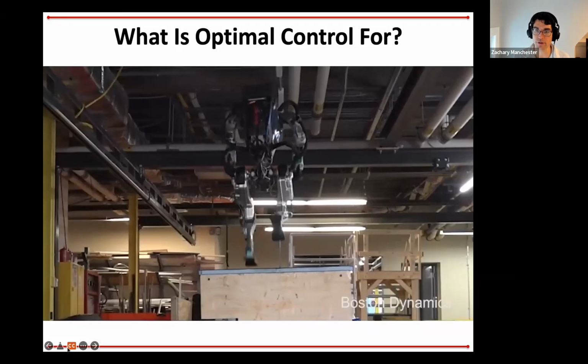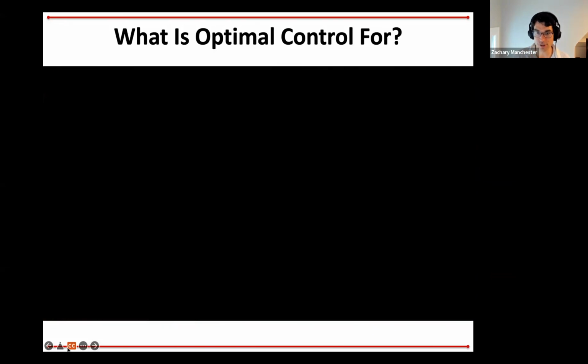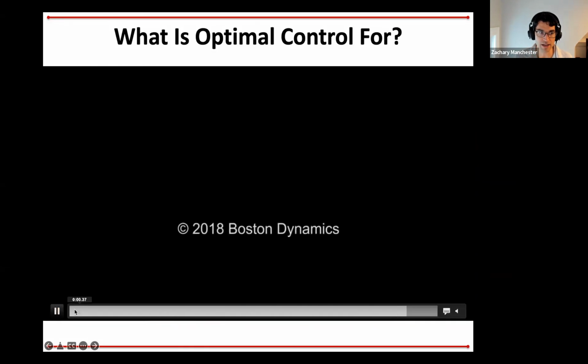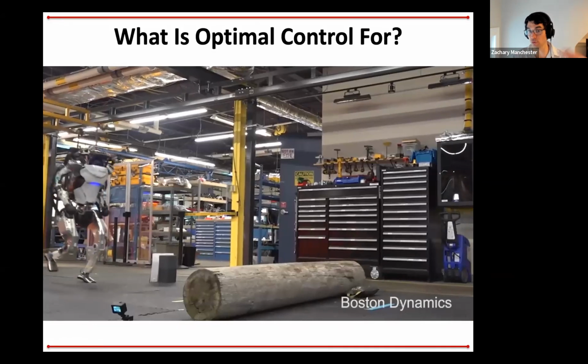So roughly speaking, what they're doing is an offline, very slow nonlinear trajectory optimization step to plan these motions. They're working with the full nonlinear dynamics of the robot, all the details in there, all the motor dynamics, et cetera. So they're doing this really intense, high dimensional, big nonlinear optimization problem offline to figure out how to move the robot.